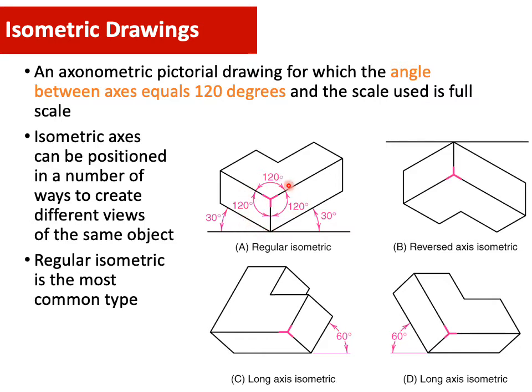Even in a regular isometric, this is the point. This is for the reverse isometric, so this will also have a point. As long as you know to mark where your point of view is, you need to start with a point with 3 axes, and the degrees between the axes should be around 120 degrees.